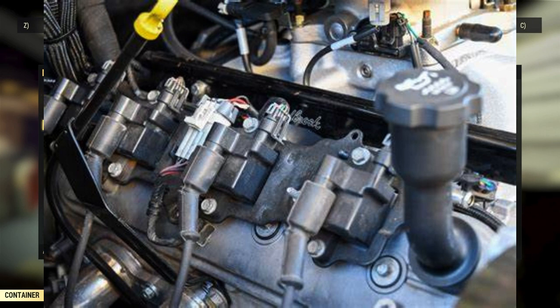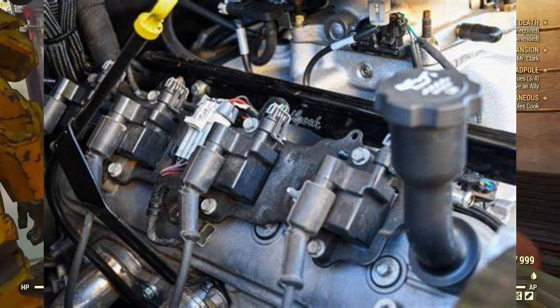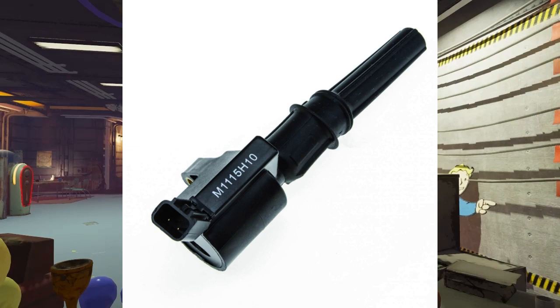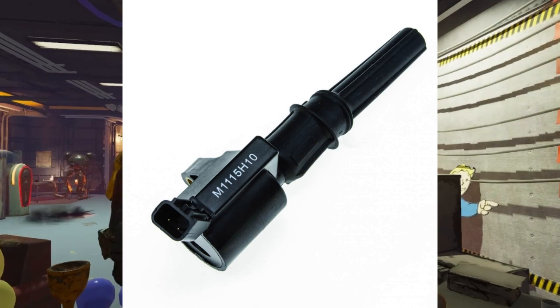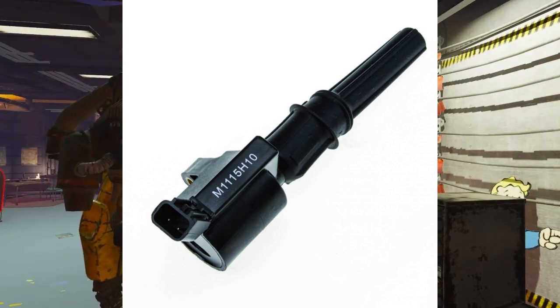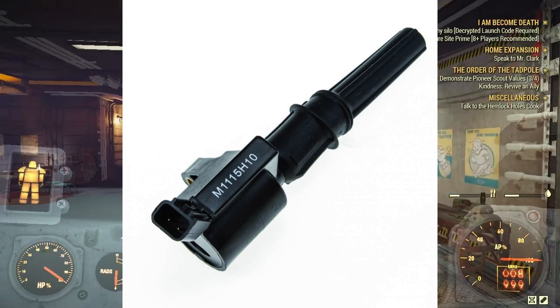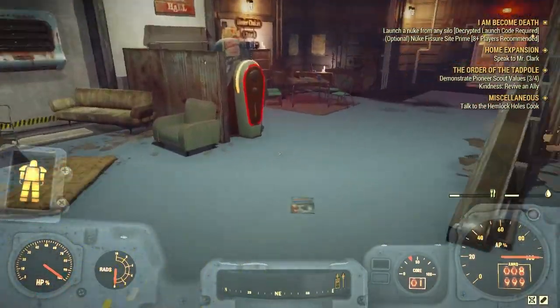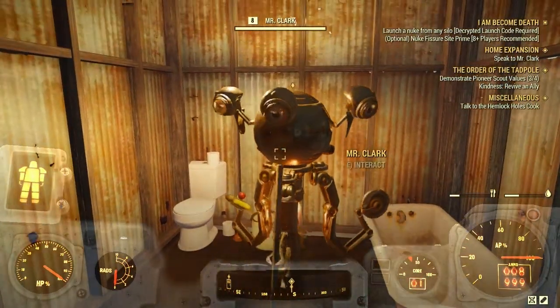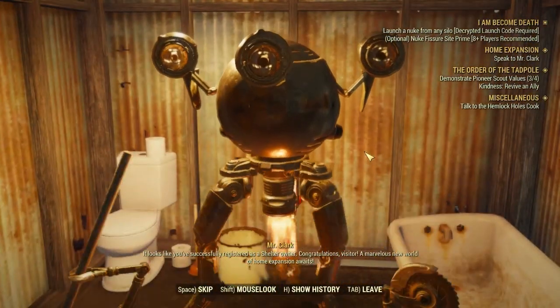For example, on LS engines, once again, Chevy Camaros, Firebirds, Corvettes, Chevy trucks, they'll have just the small wire. Or if you're in Ford land, they have this plastic or rubber tube just going all the way out. Once again, inside it has a small spring and it connects the coil to the spark plug. Like I said, different manufacturers have done it different ways. But it's basically the same technology.